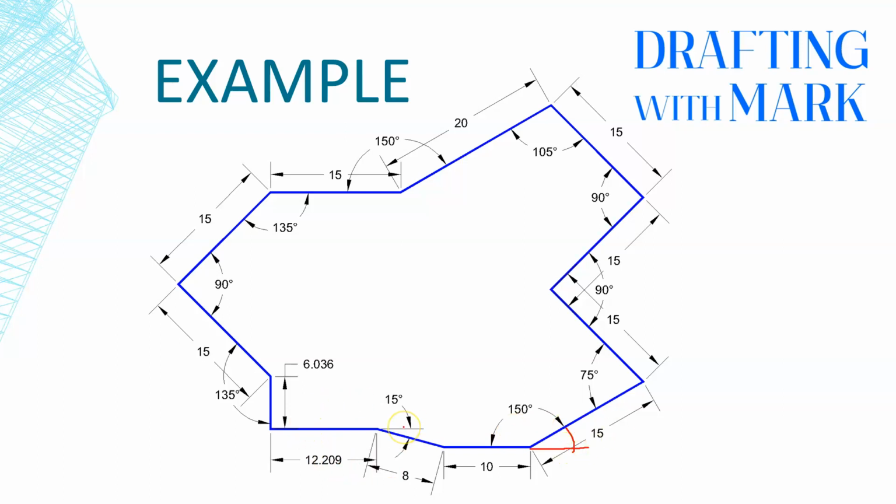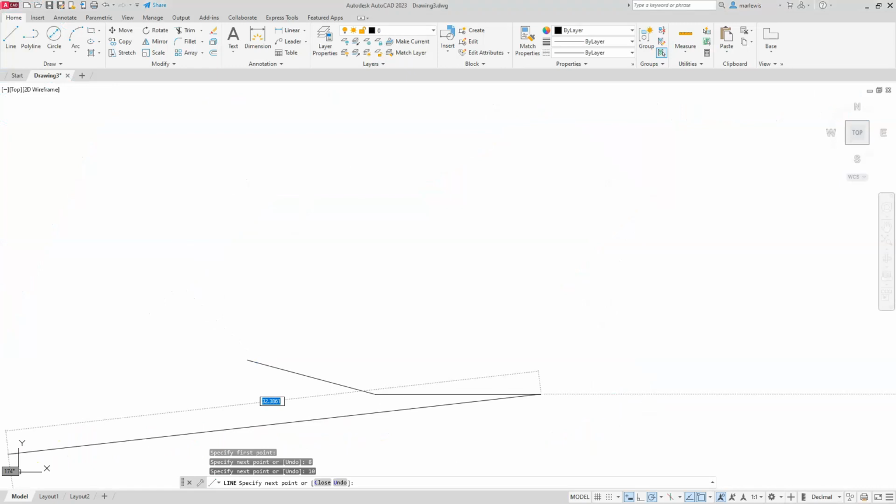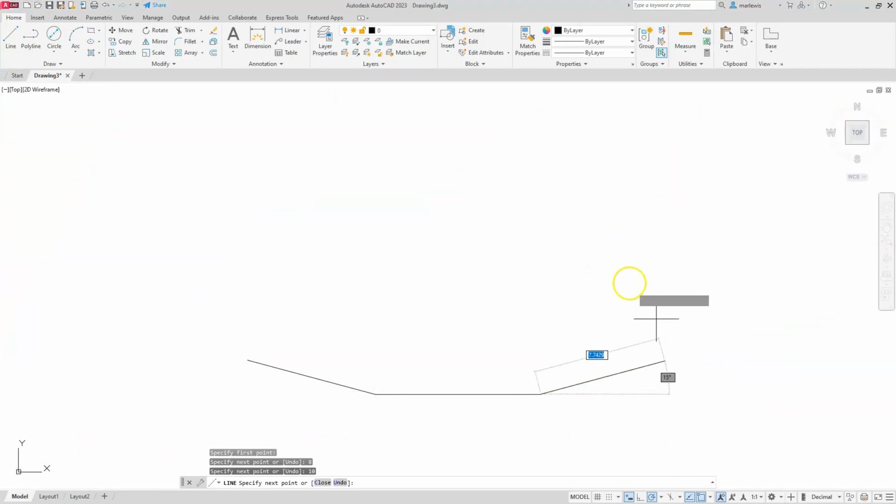It's easier to go from the other direction and make it to the 30 degrees. Okay, so what I'm implying is that we have that line created, and instead of counting all the way back here and figuring out those clicks, it's a lot easier, and you see AutoCAD is giving me my preview of that 30 degrees. So it always is going to count from that positive X direction. So that helps me out.